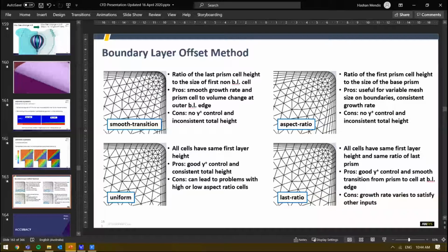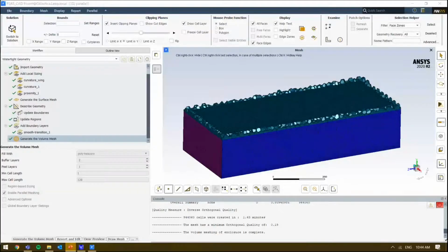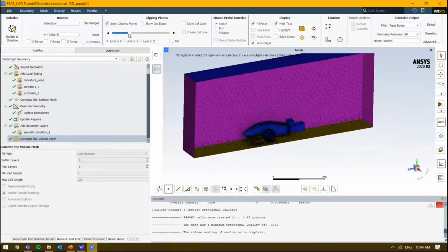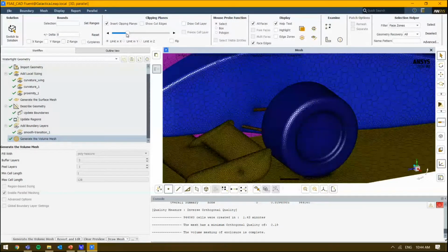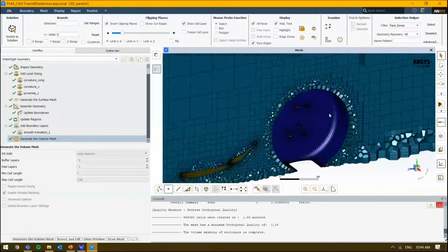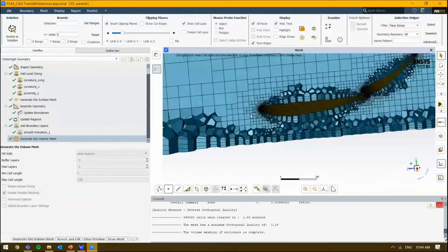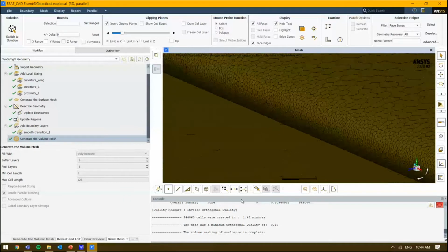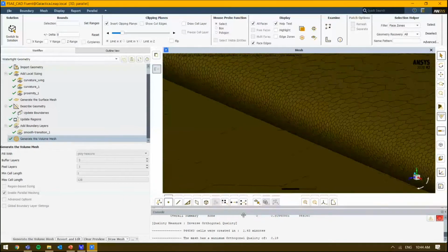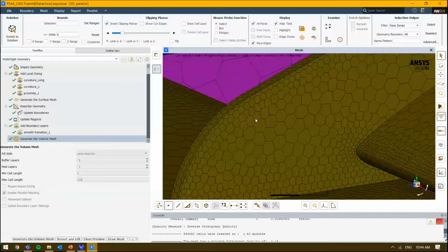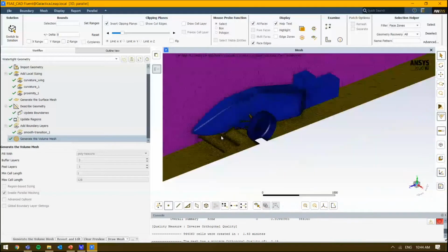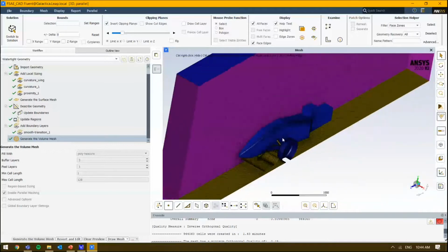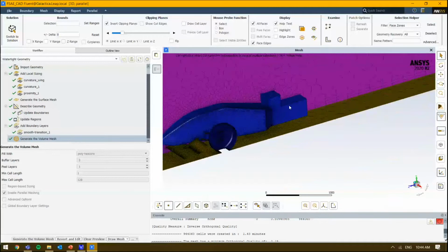So before we continue, I'm sure this grid's probably created. Awesome. Let's use my clipping planes here. If I bring this over here, I can draw my cell layer. You can see, if we get rid of this for now, I've got some poly elements around there. They're nice, they're picking up the curvature around these regions. A couple through here as well, as I expected. I've got some additional refinement around some of these regions, which is what I wanted. And it's relatively coarse around the chassis, which is fine.